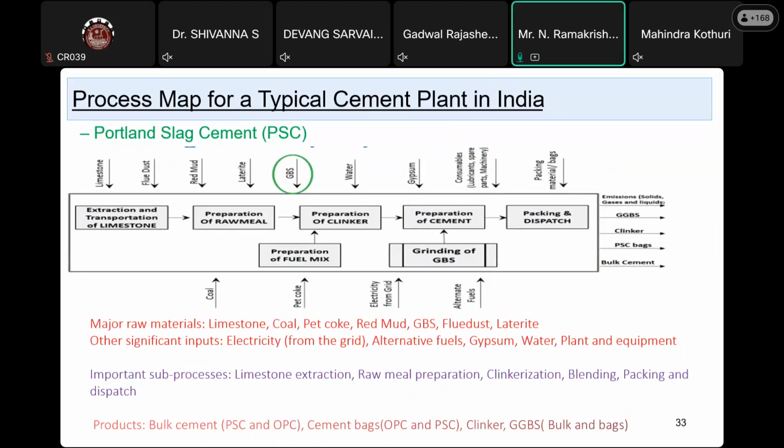At the clinker, the rate of cooling is also very important. Grinding also is very important. Why? Because these two, rate of cooling and then grinding, also will play a very important role when you go for the property studies. In fact, the strength and durability. In earlier days we were more worried about strength, but nowadays you require more durability studies on par with strength, because a lot of issues are there with durability nowadays.